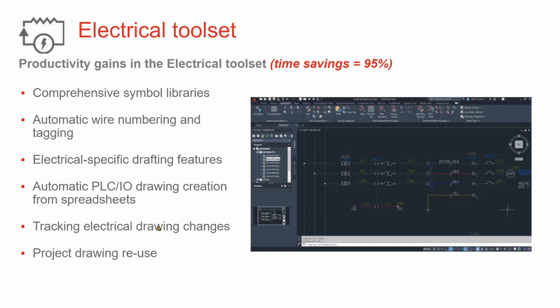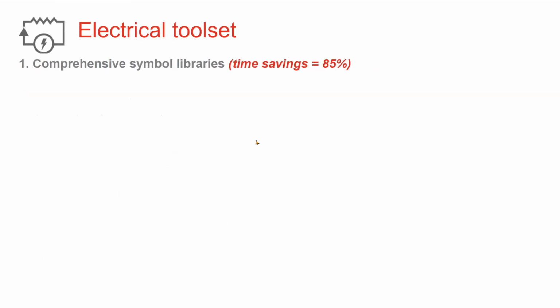One thing I didn't touch on was there's a mark verify command within AutoCAD. You put a timestamp on your project when you finish it and need to send it to your customer for approval. Then any changes your customer makes, you'll get that drawing back, and it'll show you what changes were made. It'll mark all those changes within your drawing. And then, like I said before, you can copy projects and reuse drawings. Once that's done, you can use it over and over again with just a click of a button.